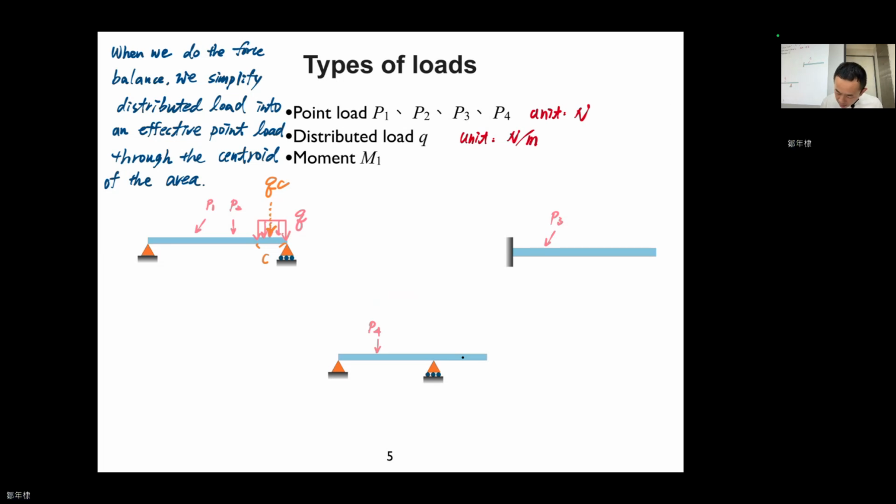Okay, so when we do the force balance, we simplify the distributed load into an effective point load through the centroid of the area.